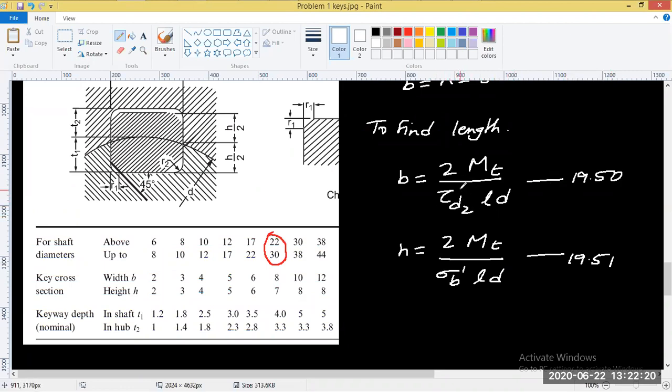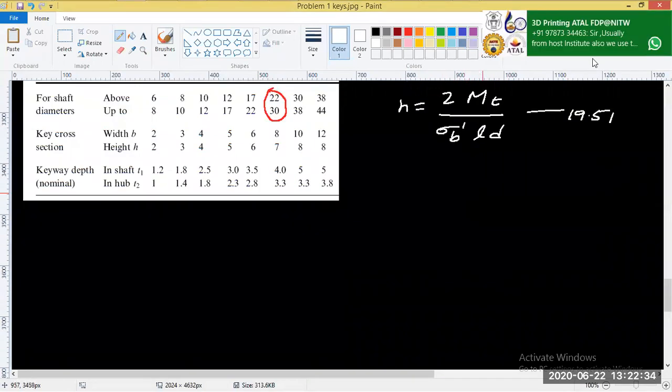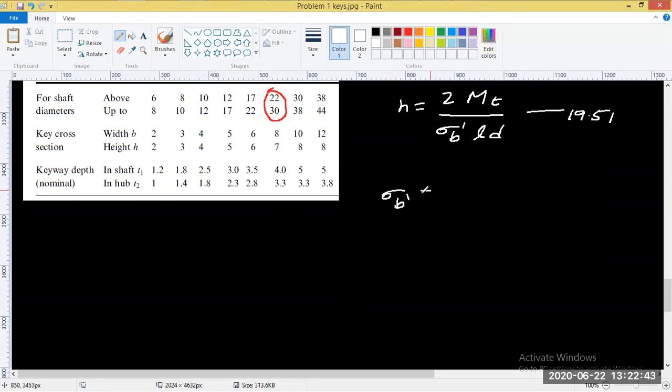So also we don't have two other values, that is crushing stress and bearing stress. So these two values we don't have, but we need to extract that somehow. Okay, how do we extract that? We know the yield stress, right? So this crushing stress is equal to sigma y yield stress by factor of safety, and just equate to this here. So this is given as 450 divided by factor of safety was 3. So just divide that and we'll get the answer.